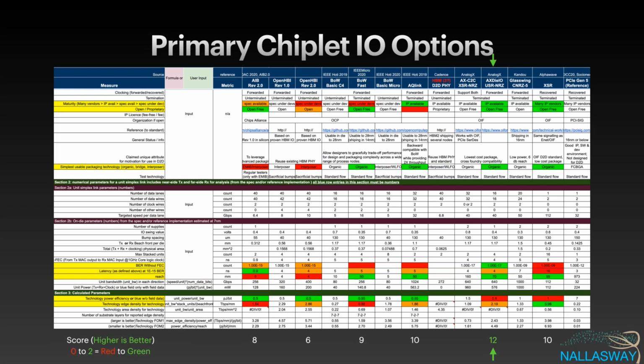Well, I'd say memory and I/O, because what I've said in my previous presentations is that memory and I/O are basically one and the same today. If you look at all these memory fabrics being talked about, essentially they're I/O to distant memory. HBM is the only local memory now, and even a DDR4 DIMM is distant in terms of our world of chiplets. So therefore, it becomes I/O.